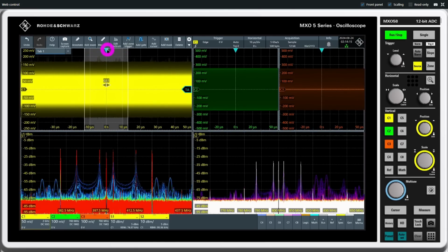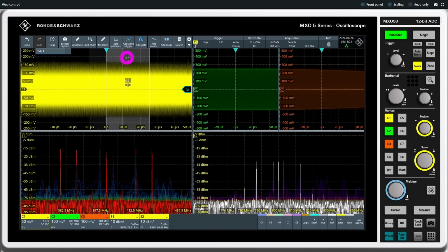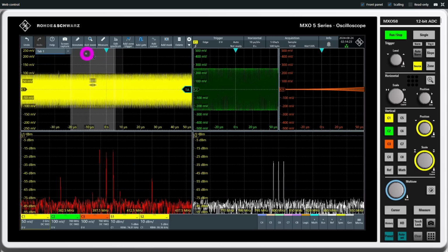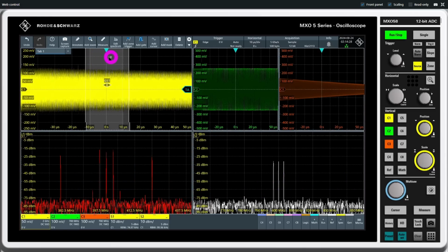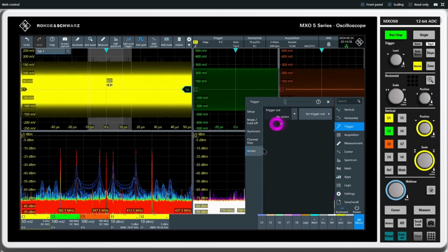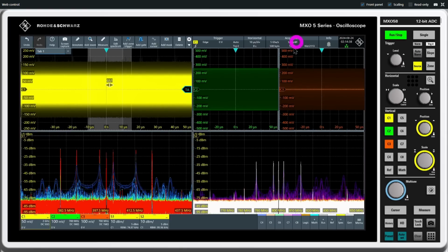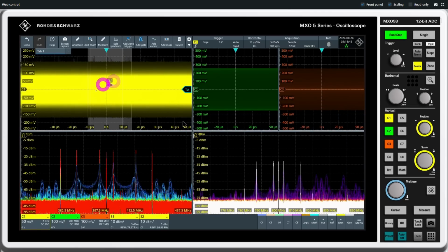And if I move it around, you can see the bottom Fourier transform calculation changes. And as I move it around, interesting things are happening. It tells us that this waveform is rapidly changing across time. By moving this around, I can select and find out where I want to analyze with respect to the trigger point. Now remember, this is still basically just an edge trigger that I'm doing, nothing unusual regarding that. And we're taking, let's see how many acquisitions we're actually making, about 2.4 thousand acquisitions per second, which has to do with how fast this thing can trigger on this waveform.